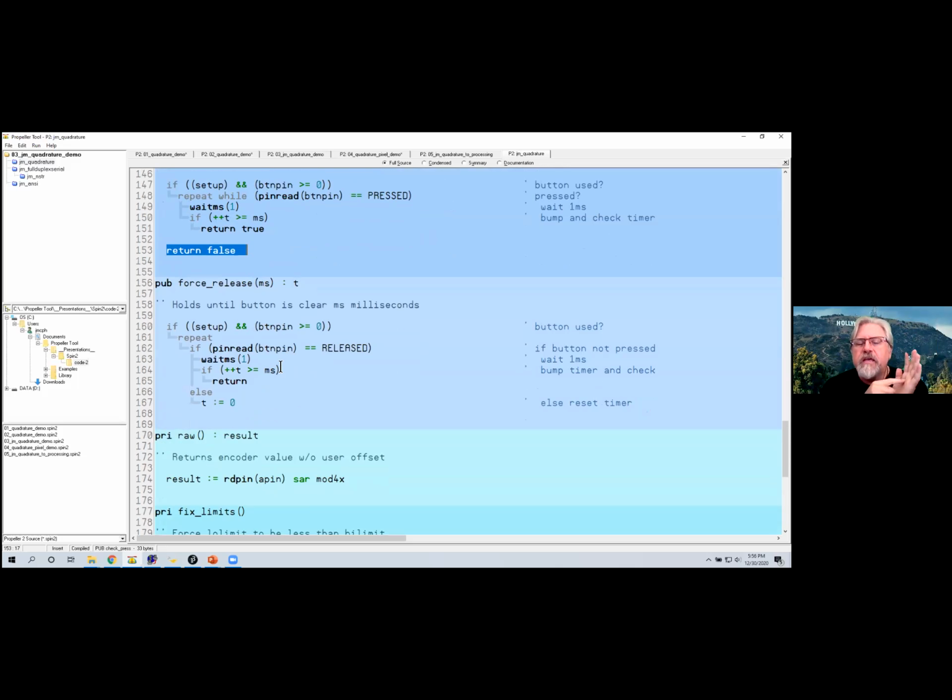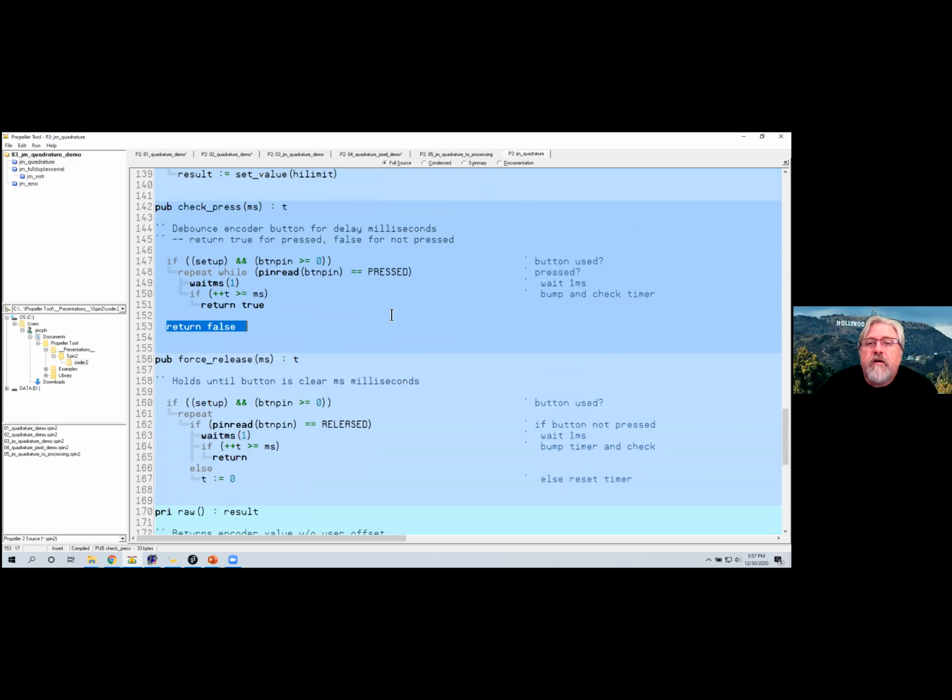And in fact, sometimes if you click on something on screen and then hold the mouse button down and drag and release, it doesn't do it because it's looking for the release event on top of that. In this case, this is where we're looking for a release event, to make sure that the button is not cleared. That way we don't have something happening too quickly. We want to say, hey, press a button, let it go, and then we'll do something. So it prevents things from running away. So this is all of the code now, and we can do